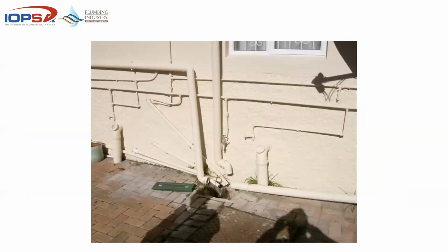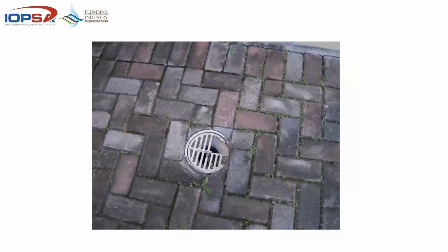But yet when we get to site, you'll see that there's always that low-lying area where we have people discharging downpipes into the gully, because if they don't, then that flat paved area, you can see even the overland flow ends up in that specific gully there. And then you get the scary ones where they actually remove the rodding eye covers and install grids, and then they complain about smells.